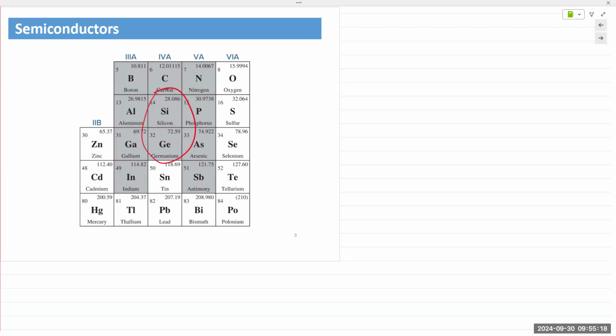Two reasons why. Silicon is the second most abundant element on this planet, right? So it's very widely available. And then early on, research was conducted into silicon material. When you create semiconductor devices, you need material with the highest purity possible. You're talking about like 99.99999 long 9%. Okay. So out of millions and billions of atoms in a single piece of material, you'd have impurity levels, meaning external material, of very few parts per billion atoms.